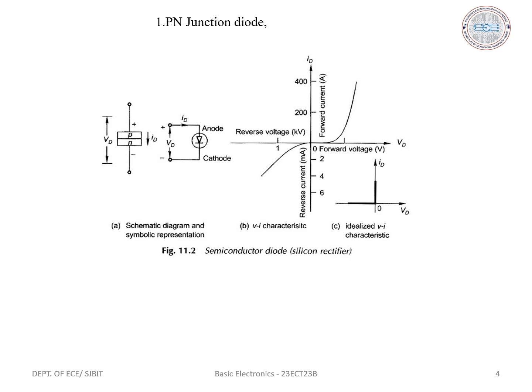In the region A to B of the forward characteristics, the forward voltage is small and less than the barrier potential. Therefore, the forward current flowing through the diode is small. With further increase in the forward voltage, it reaches the level of the barrier potential and the width of the depletion region goes on decreasing. As soon as the forward voltage equals the barrier potential, the current through the diode increases suddenly. The nature of this current is exponential. The large current in the region B to C of the forward characteristics is limited by connecting a resistor R in series with the diode. The forward current is of the order of a few milliamps.